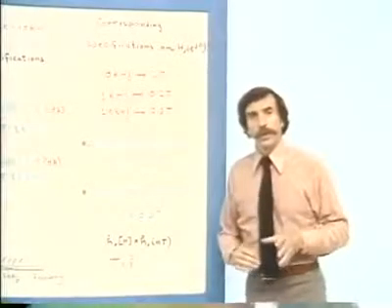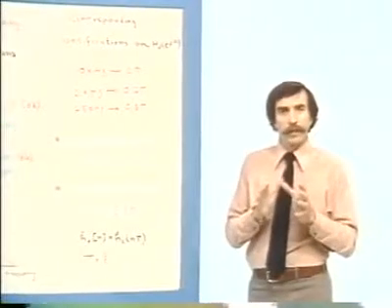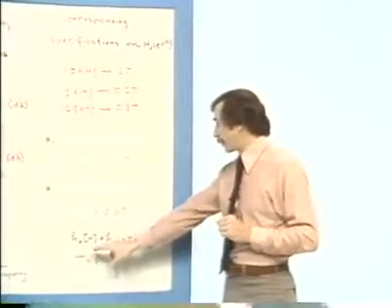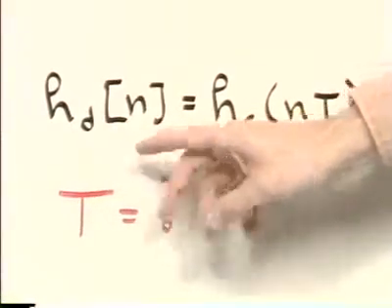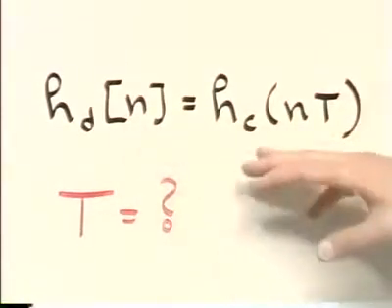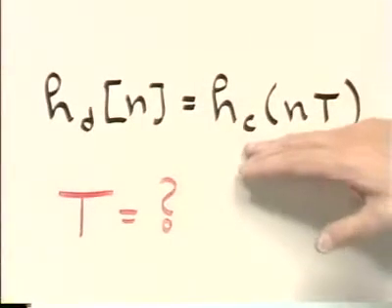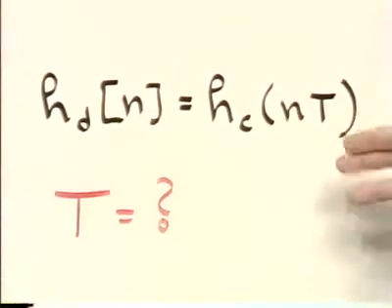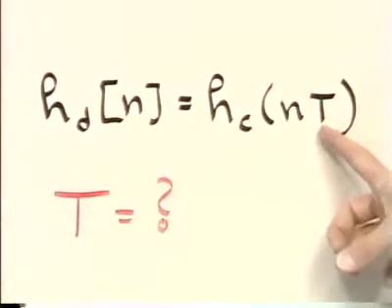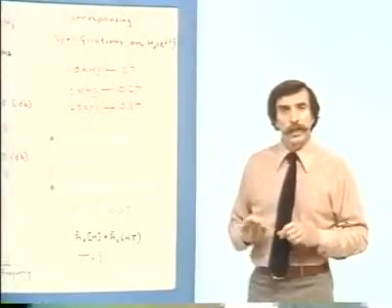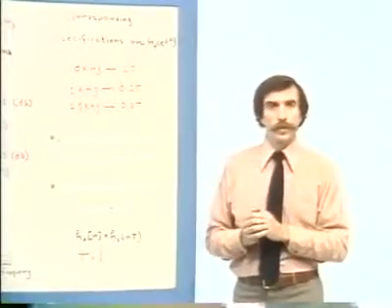And we now want to design the discrete time filter using impulse invariance. Now, in impulse invariance, as you recall, it corresponds to generating an impulse response, which is a sampled version of the continuous time impulse response. And there is a temptation, naturally, to think of this parameter, capital T, as necessarily identical to the sampling in the system in which the filter is going to be used.